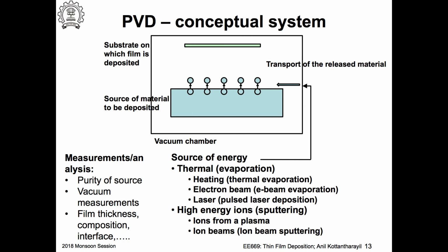Now, if you look at a PVD conceptual system, so very simple. You have a chamber, okay? It's a vacuum chamber, and you have the substrate on which you want to deposit the film, and then the source of material to be deposited, and you provide some energy.